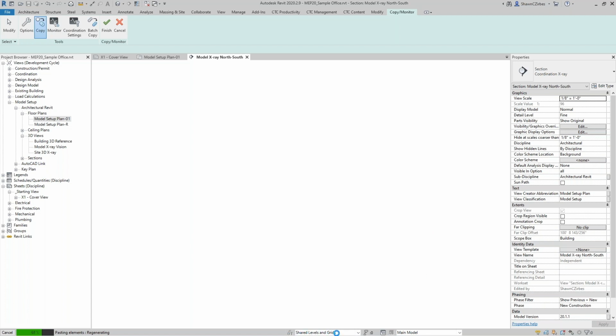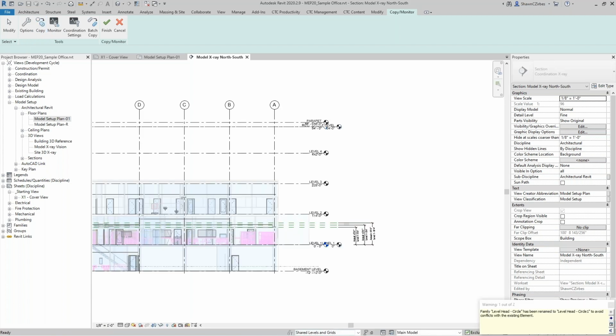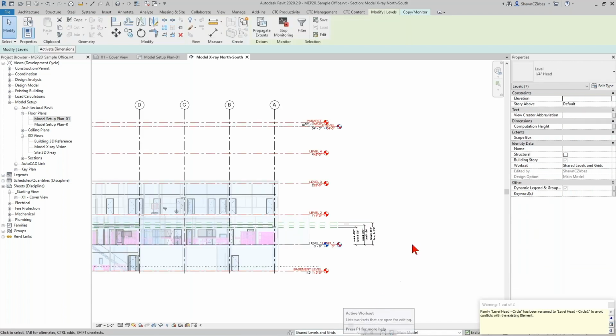And then all of these levels and the scope boxes we're about to copy and a bunch of other things, the grid lines, they might go to the wrong work set, and that can cause frustrations. So I like to just err on the side of leaving this as the default when we first save that model. And then that just saves me a bit of headache, because usually it's me who's starting these models up, honestly. And it just makes it a little easier for me. I'm just giving myself a little leg up in the game. So keep an eye on that when you're saving your own templates. Make sure that the work set is correct.